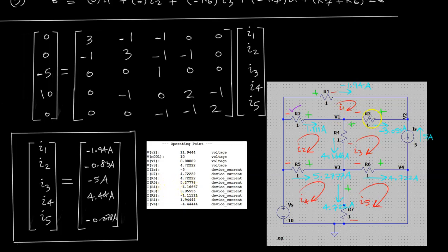Let's see here. So with this guy being plus, it tells us that our assumed direction was incorrect. Let's see here. What do I have? So okay, this agrees, because let's go ahead and write the LTSPICE one. LTSPICE results in purple. So LTSPICE is telling us that the current through R2 is going to flow opposite.